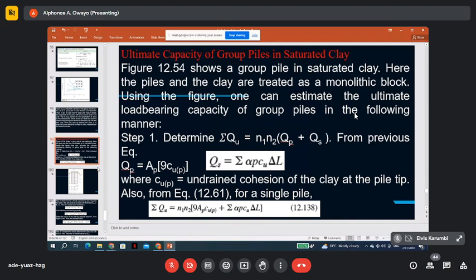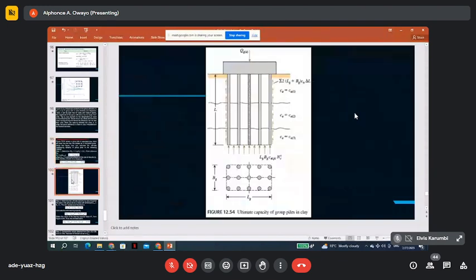So you find the equivalent length, which we already know how to determine, equivalent width, all right, and the representative Cu, which you need to sum. Actually, that's the reason for the sum here. Okay, alpha. So alpha, all these things are the same. Now P is the equivalent perimeter because you're talking about a pile group, okay, which we now know how to find.